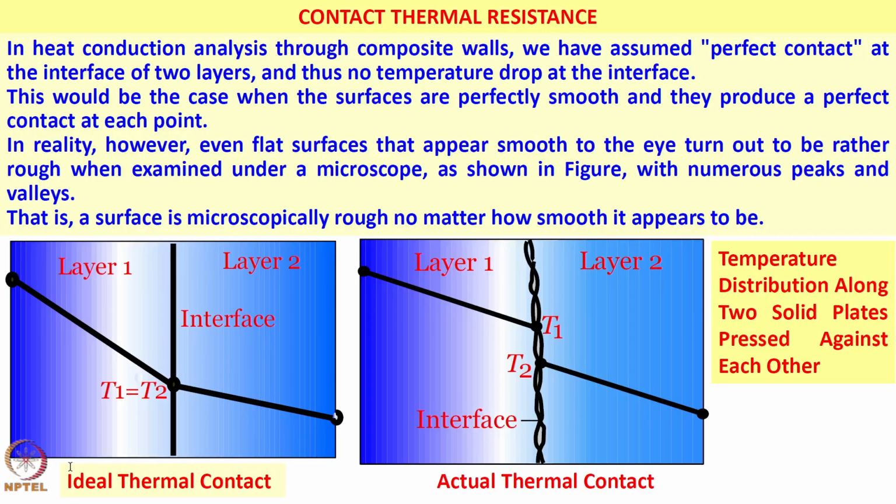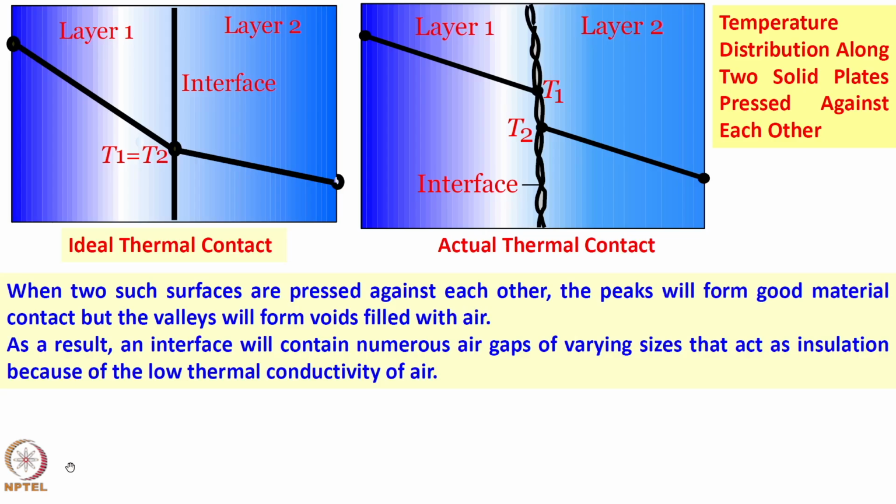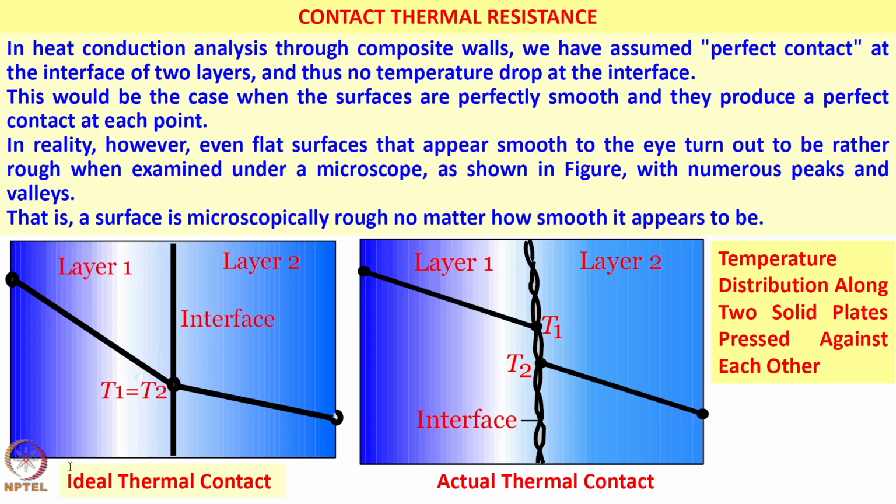Okay. We also spoke about thermal contact resistance, and we said it is a function of the interstitial spaces, etc. So, air is going to be a bad conductor of heat. So, once you have an air gap, there will be a temperature drop, and that is not a good thing for heat transfer. So, you can apply some pressure, you can use thermal contact grease, which will be able to reduce the temperature drop, reduce the contact resistance.